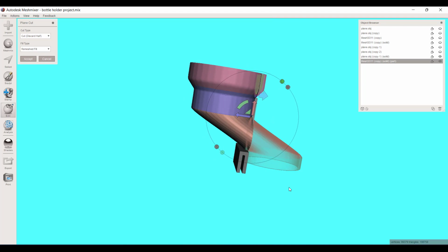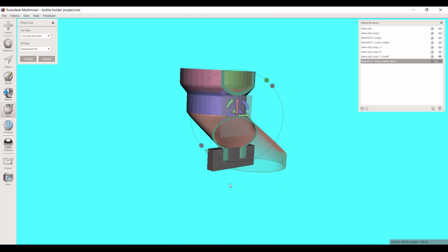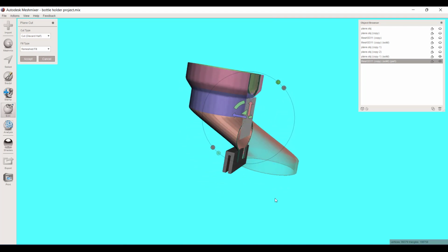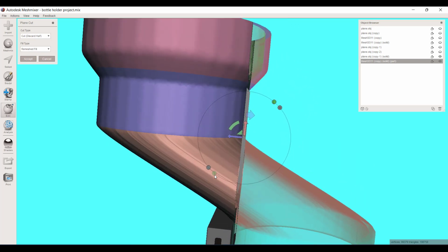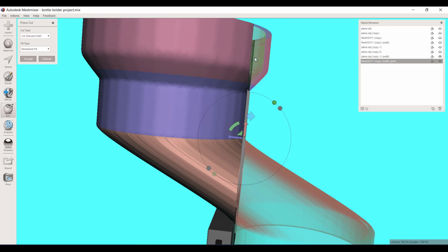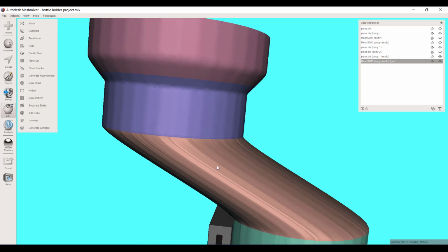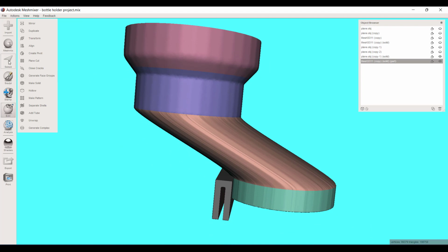Depending on how much work you want to do with this, you could go with that shape. That actually works. But what I was going to show you is when you do a plane cut, it's going to cut indefinitely through all parts of your shape that you've generated. What if I don't want to do that? All right, what if I want to leave this fully intact?